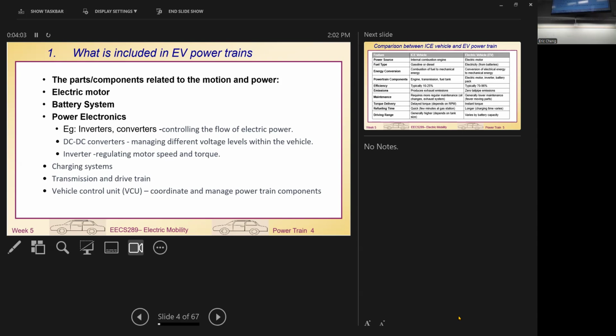Or sometimes if the charger is only the power point charger, level 1 charger, level 2 charger on board the vehicle, you're only using 120 volts. But this voltage is not good enough for the battery voltage. You need to step up the voltage. So you also need a DC-DC converter to increase the voltage from your main power point to your battery voltage. So somehow we need to convert the DC voltage. So that's also the function of the DC converter.